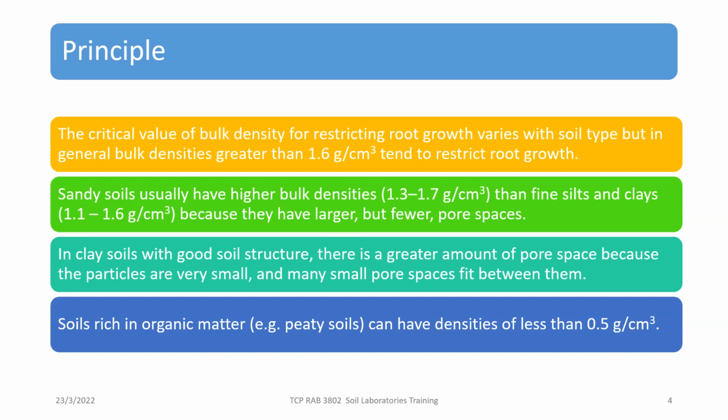And this is the reason that yesterday I think Abir mentioned the issue of addition of organic matter to the soils to improve or to reclaim saline soils. I responded that the organic matter itself does not have to do with the salinity, but it will improve the soil physical condition, and this will improve the possibility of leaching of salt from the root zone.